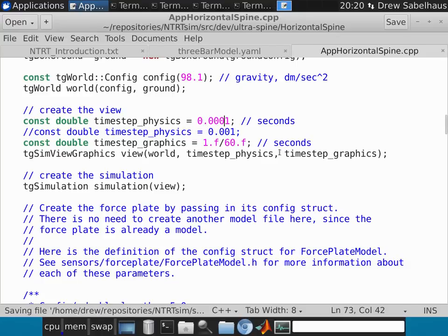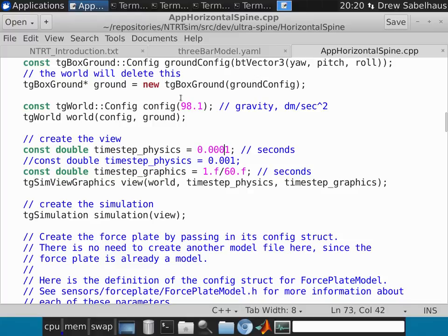And then gravity. If we needed to change any scaling, one of the things that is talked about a little bit in NTRT, one of the other ways that things could go unstable besides having too large of a time step here is to have your structure be too small. So if anyone has done a fluids class, for example, or a heat transfer class, for any of the mechanical engineers, if you remember dynamic similarity, all these non-dimensional numbers, if we keep the Reynolds number constant, then the flow is the same in these two situations. There's a similar thing that we can do in here.